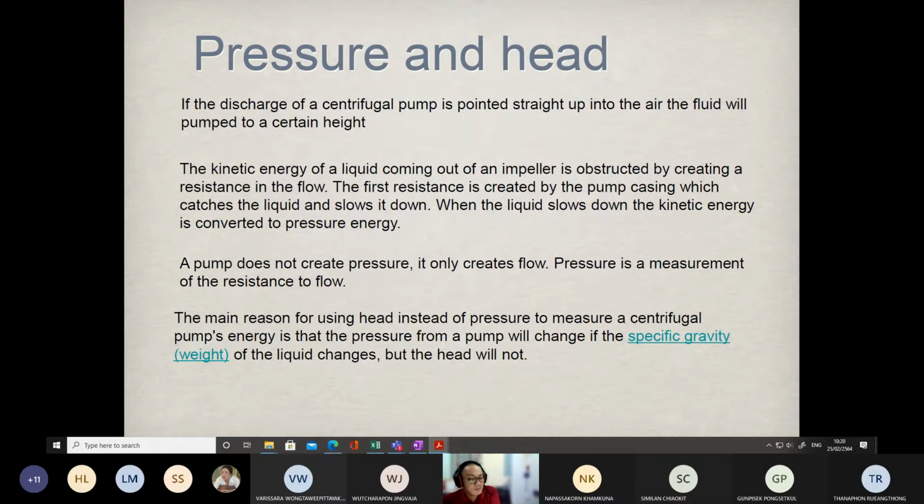That is the density, but it's also the same as the specific gravity. This amount can change sometimes, varying depending on the temperature. But if you divide by gamma, the problem with regard to the pressure is gone. So it is better to express it as head, which is normally expressed in terms of water column height, meters, feet, and so on.